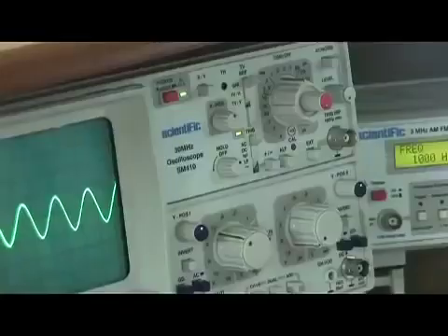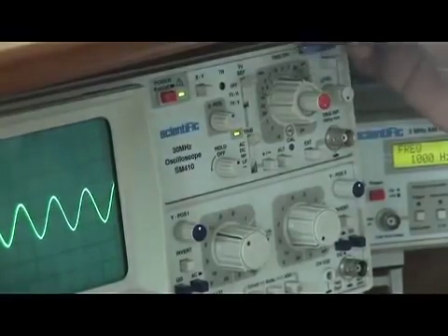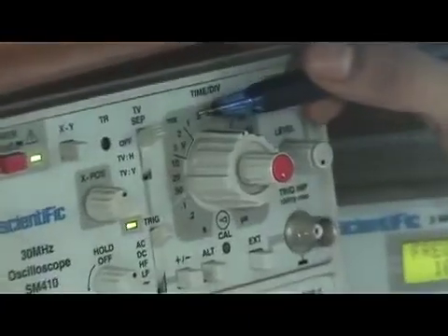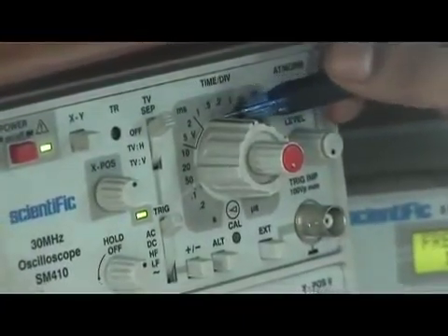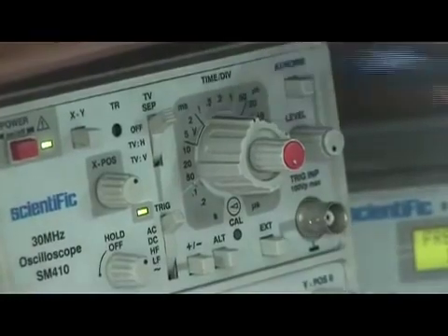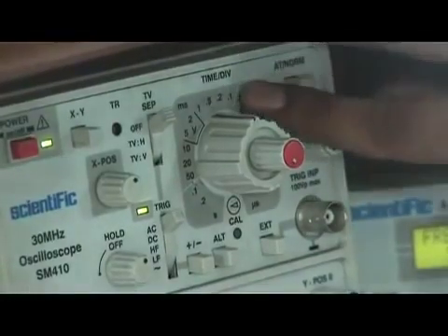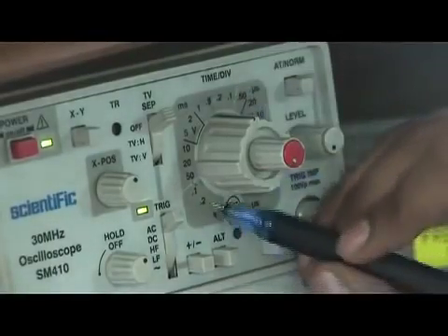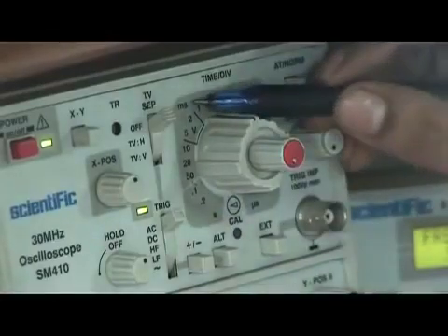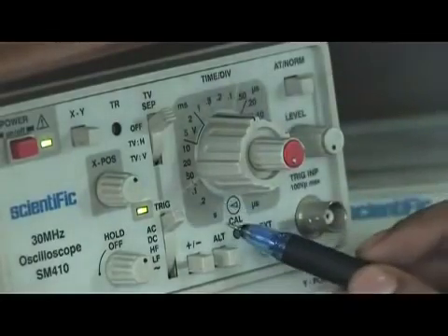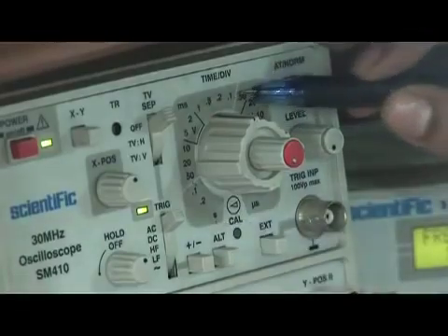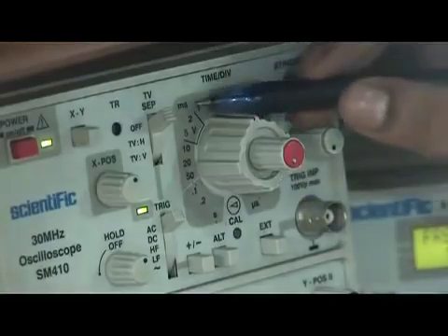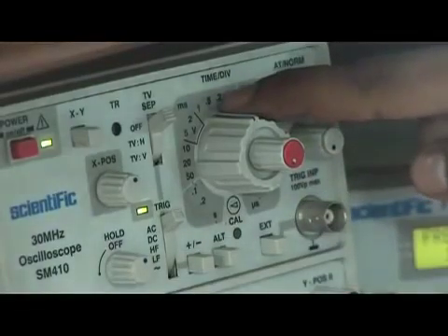So it is 2 into where this knob lies. See, there is a line here, and it lies at 0.5. So 2 into 0.5 is how much? 2 into 0.5 is 1. And what will be the unit? From this gap till this small gap, the unit will be in milliseconds. From this gap to here, the unit will be in seconds. From this gap till here, the unit will be in microseconds. But right now we are in the millisecond range. That's why it is 2 into 0.5 milliseconds.